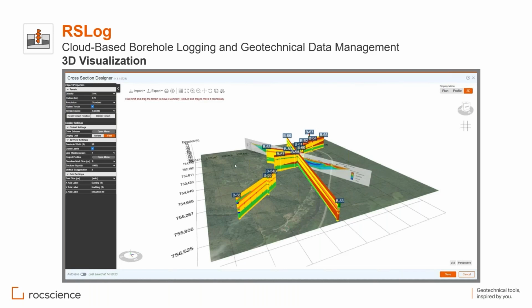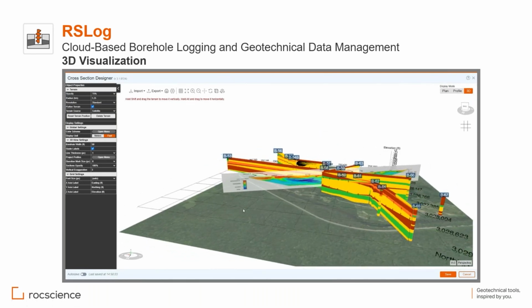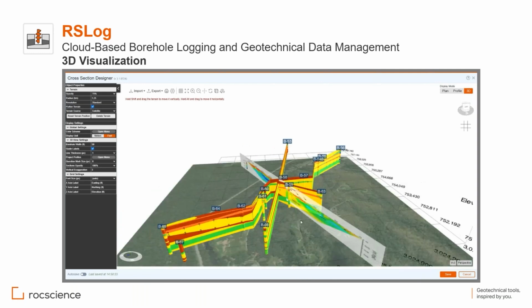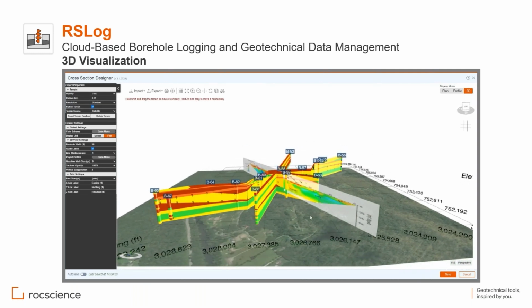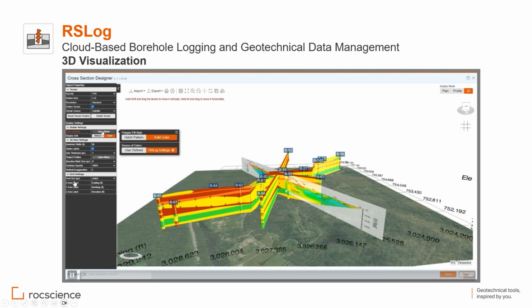The other component that we see here on this page is the map. You see that in the background here, we've added a satellite photo. You can choose between map and satellite, and then you can generate a terrain model essentially automatically in the cross-section designer without importing anything. What we do is essentially send the project site location to different map servers, and we obtain LiDAR data.